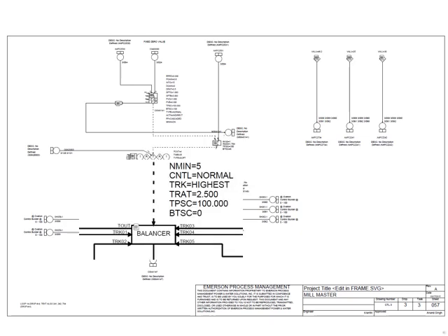Below it is the balancer. It monitors the modes of up to 16 downstream algorithms and performs a user-defined type of tracking when all the downstream algorithms are requesting the upstream algorithm to track. A special configuration of the balancer algorithm enables it to be used to balance the outputs of several downstream auto manual stations.